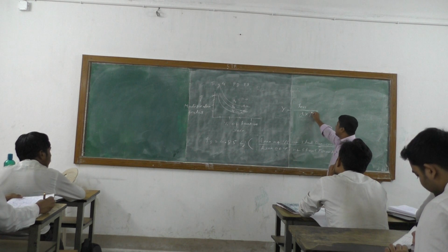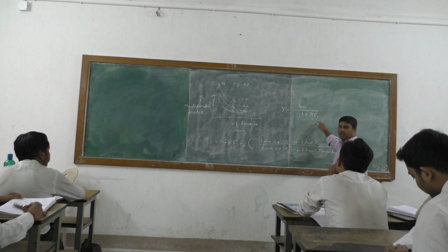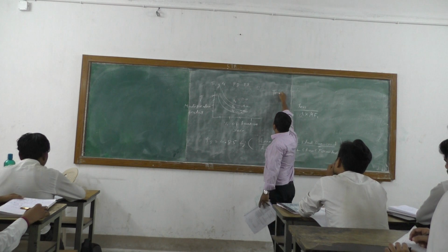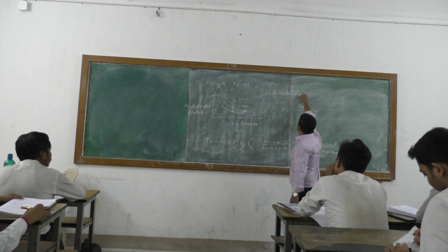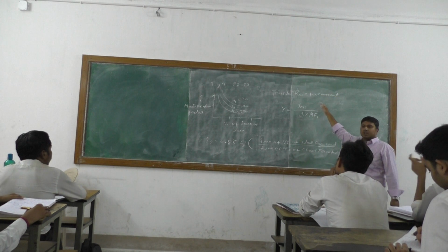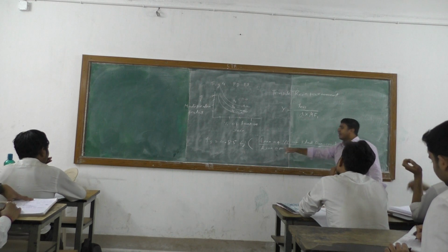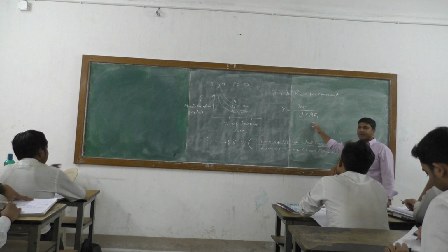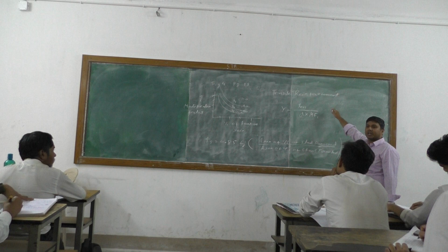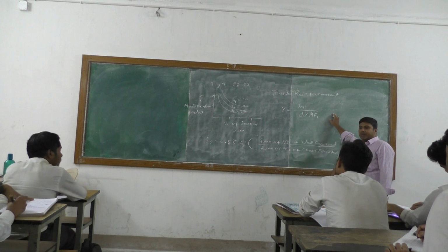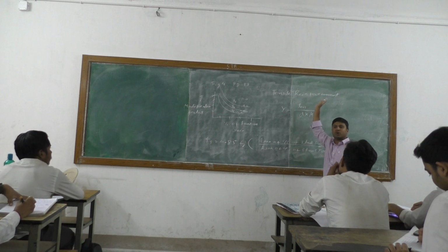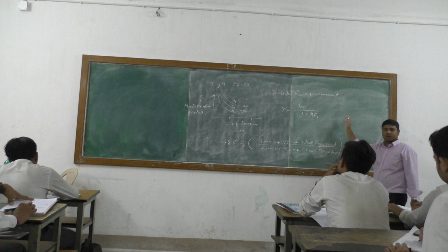And we have to just multiply the modification factor with the value of L by D for tensile reinforcement. Then we can find out L by D into the modification factor, the value that has come. From here we can find out what should be the maximum depth of the beam or slab according to the tensile reinforcement that is designed. Okay, this is one of the checks you can see. Understood?